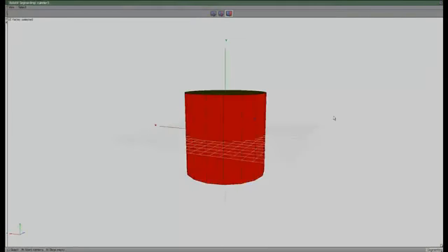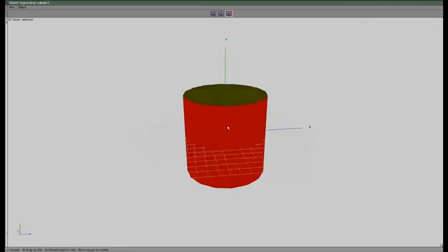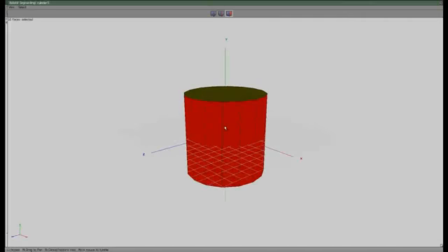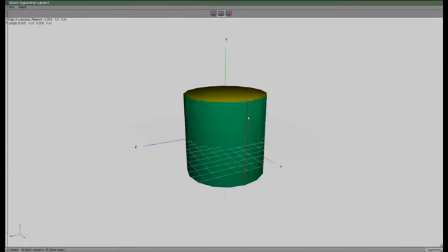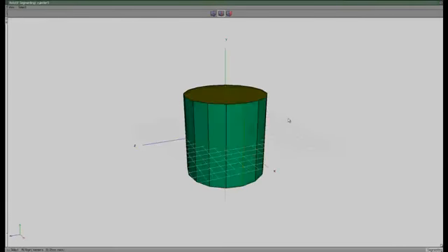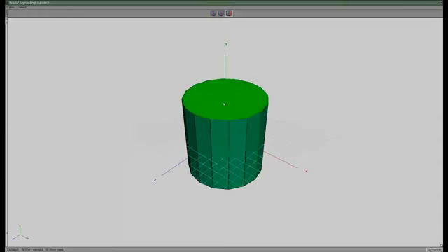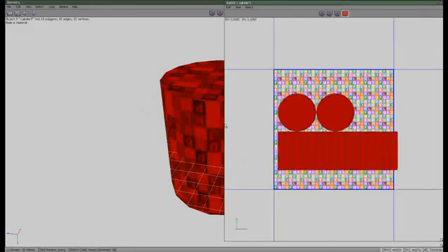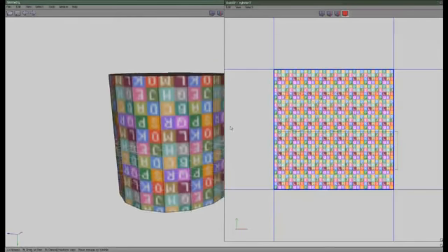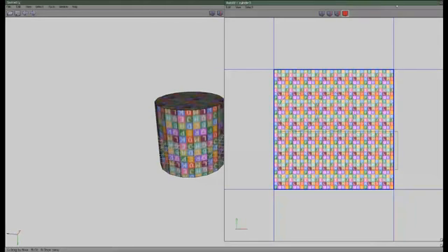So obviously this right here, the centerpiece is cylindrical, so that's not really going to unwrap properly. So we need to define a seam somewhere in the middle. So I'm just going to pick this one. It doesn't really matter which one here. So this is going to be our seam, and it's going to unfold like this and like that onto a flat plane like so. So we can right click again and do unfolding, and there we go. That's it. We have a very nicely unwrapped cylinder, and that basically took us a second.